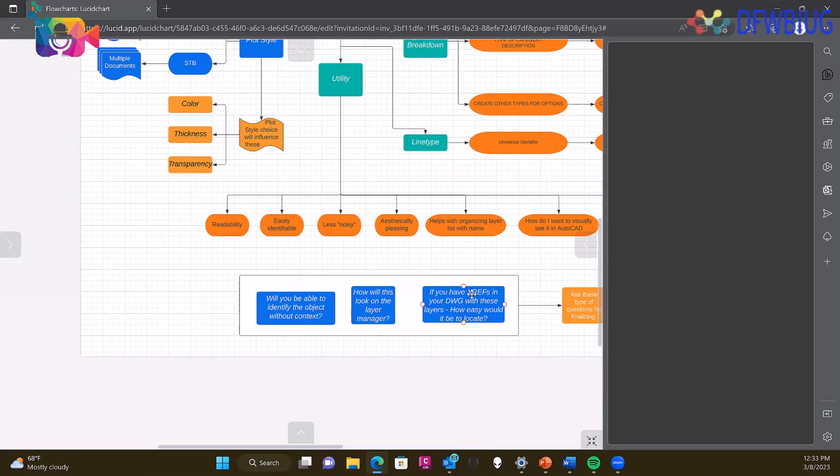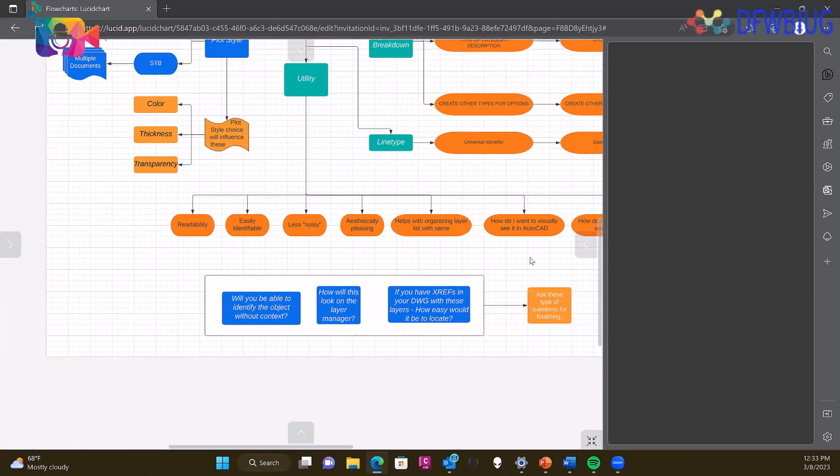Jump in. One of the reasons I don't use the National CAD Standard is they use 4 letters for everything. And if you got new employees, they don't understand some of these initials. So they have to look up descriptions, they got to look up a handout. I try to dumb it down, spell out some of these things. A good example, I spell out storm, but they leave out the O in the National CAD Standard. Yeah. So things like that kind of annoy me. Look, I'm trying to make it very simple for somebody getting into CAD for the first time. They won't know what some of these initials stand for.